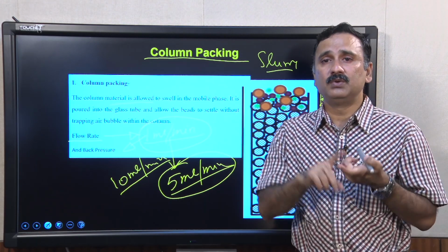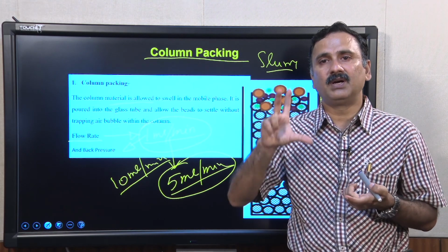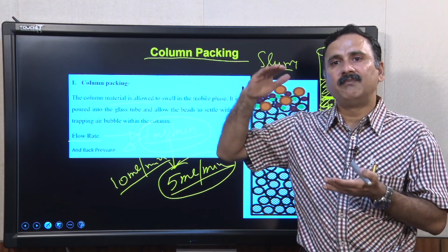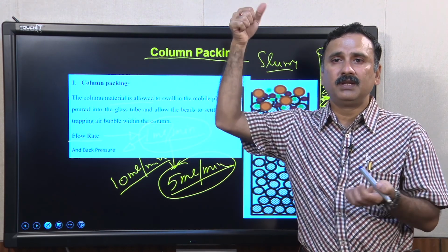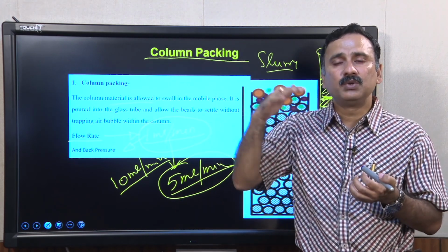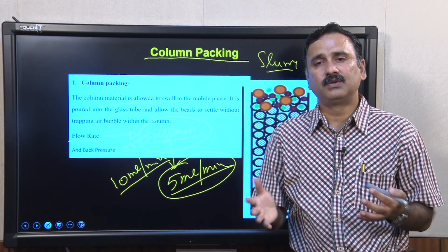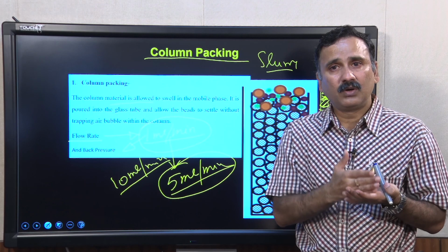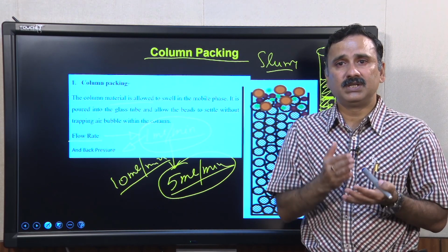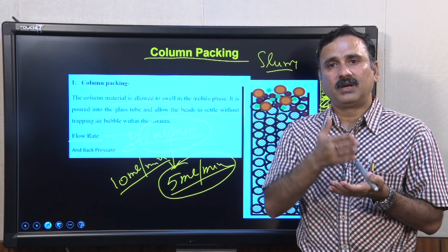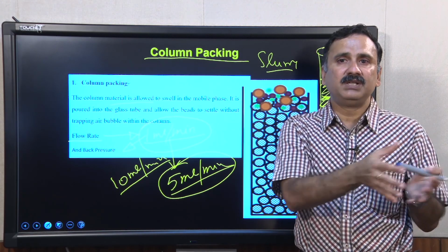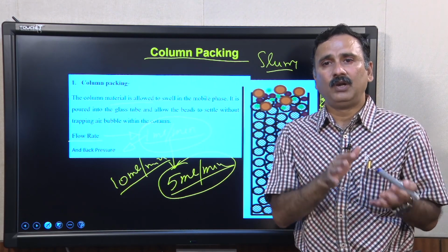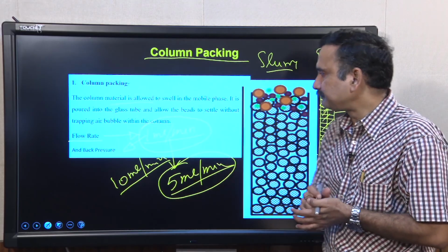It is going to reduce the fractionation range, because earlier you had 1000 plates within this column, and now since you have compressed this column, you are changing the pattern. So, you are going to change all the parameters. For example, you are going to change the void volume and all other parameters. So, your relationship between the distribution coefficient versus log molecular weight for the previous column is not going to hold for this column as well.